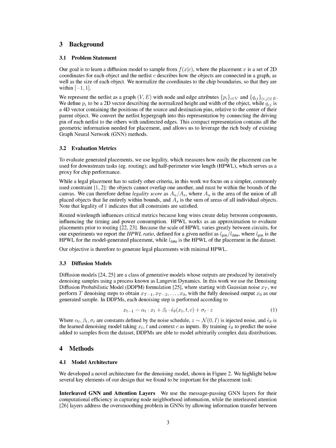Traditional macro placement methods rely on commercial tools and human input, which can be time-consuming and costly. To address limitations of existing reinforcement learning (RL) approaches, we propose a novel approach using diffusion models that can be trained offline and applied zero-shot to new netlists, resulting in near-optimal chip placements. Our model architecture combines graph convolutions and multi-headed attention layers, and we generate synthetic data to achieve competitive results on benchmarks without training on realistic circuit data.